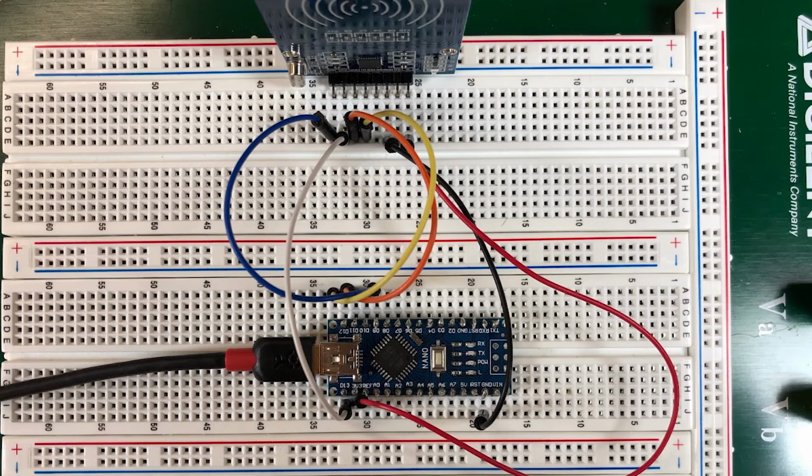The Arduino uses an AVR microchip that provides dedicated SPI communication hardware with certain pins dedicated to be MOSI, MISO, SCK, and SS. Since these pins vary in location by board model, they are also tied to an ICSP header, which are on the 2x3 grid of pins at the edge of the boards. On the Nano model, which we will be using, pin 10 is SS, pin 11 is MOSI, pin 12 is MISO, and pin 13 is serial clock. I've wired up these pins to the corresponding pins on the sensor.